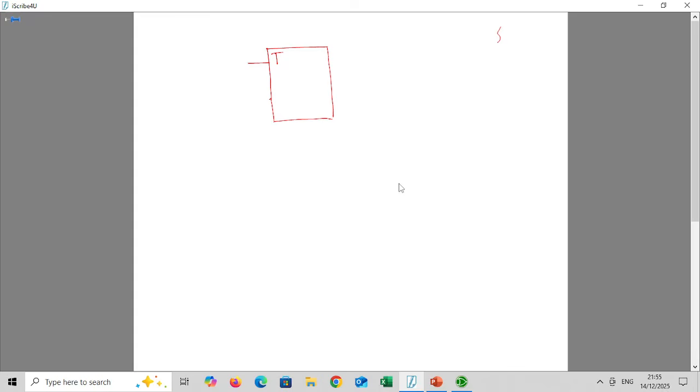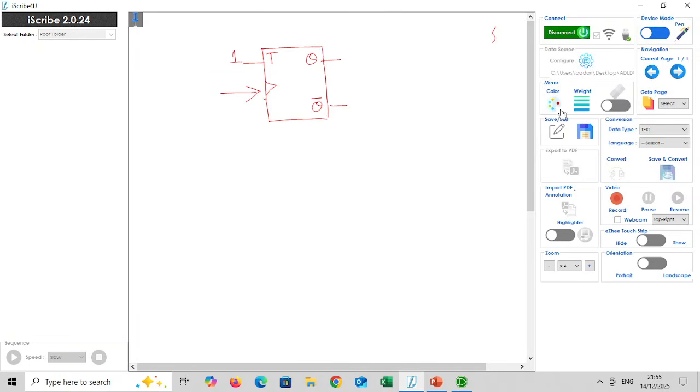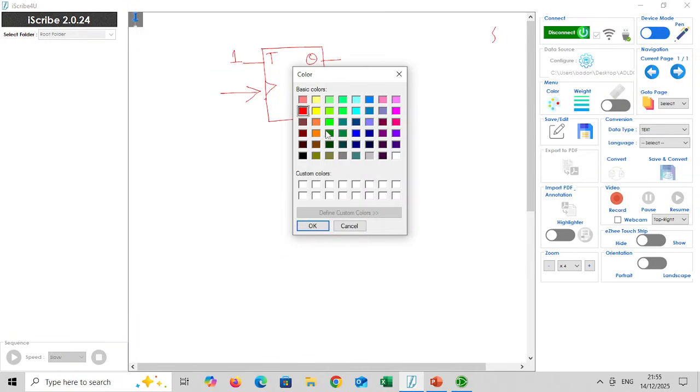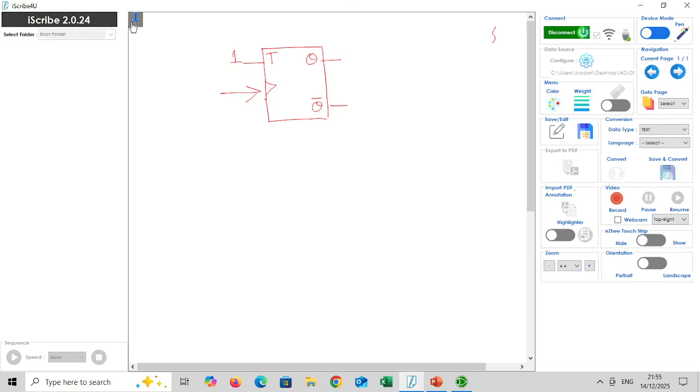disables the toggling nature of the T flip-flop. So let's assign 1 for that. T flip-flops require the clock for their working. So let's assume a positive edge triggered T flip-flop and two outputs, normal output and complementary output. Let's apply the clock frequency to the T flip-flop and analyze the relationship between the input clock frequency and the output clock frequency.